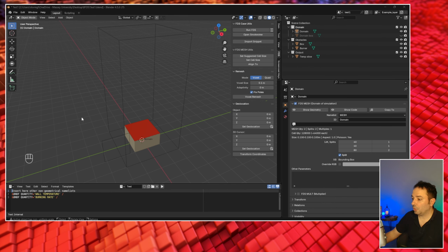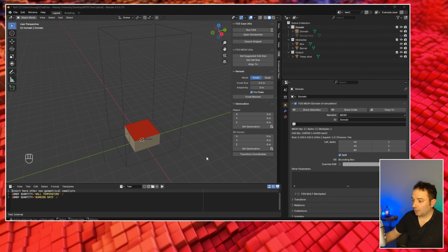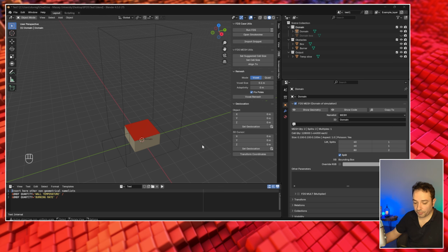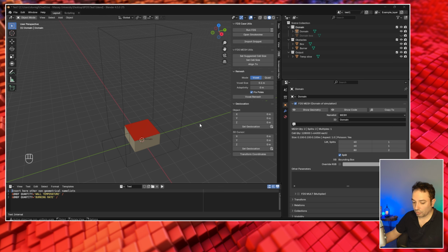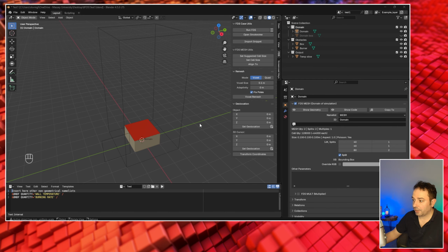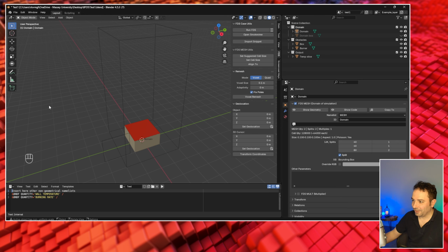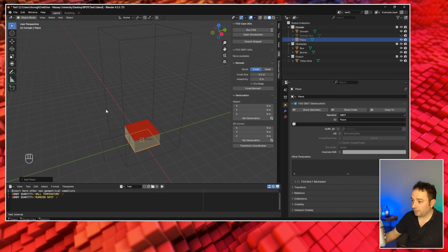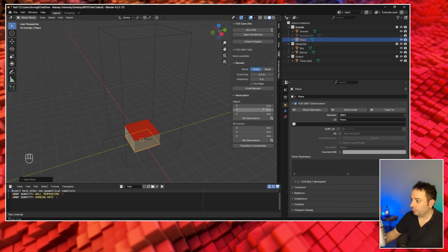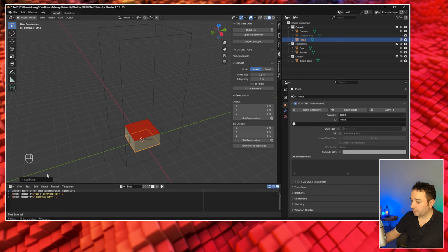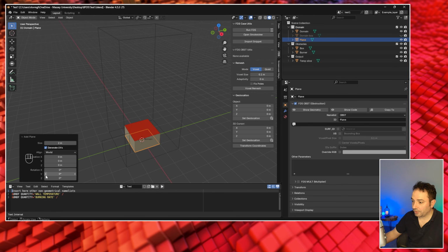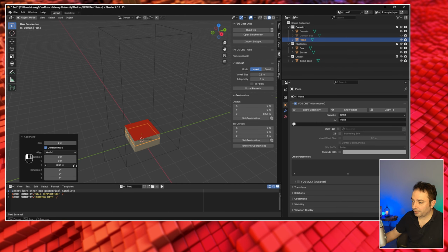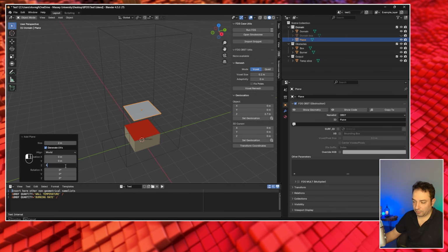So let's go and modify this scenario even further. I'm going to put a new slice here and measure velocity. So to do it, we have this option here. You press Shift A. First of all, we need to be clicking this domain, Shift A, and I'm going to add a plane. So you can see that the plane has been moved below our object. I'm going to open this panel here and not rotate it. The rotation is fine. I'm going to translate it, and let's say that we want it at 4 meters.